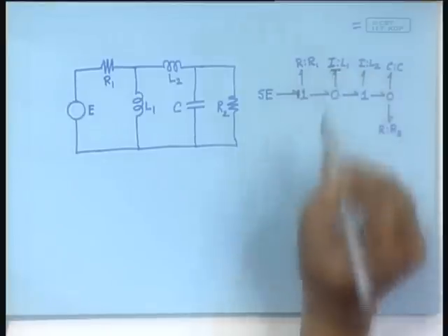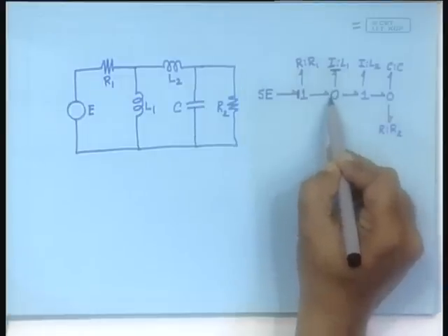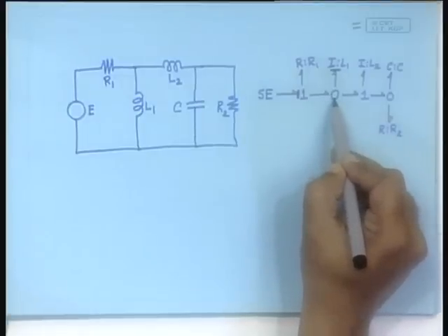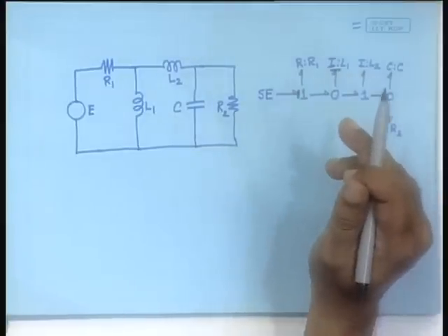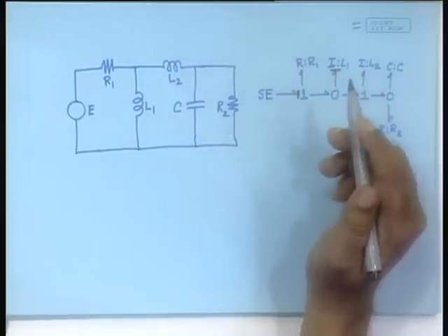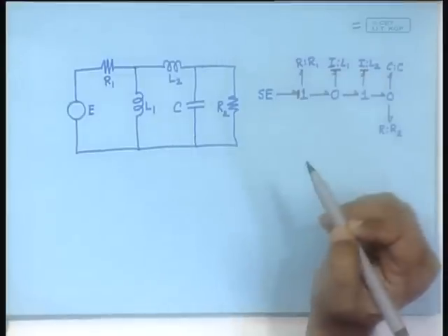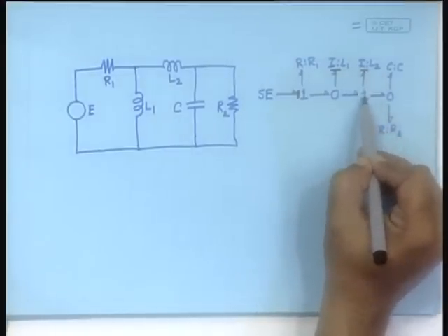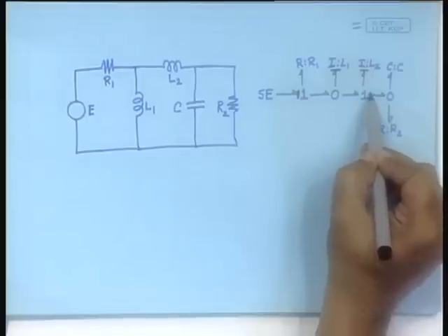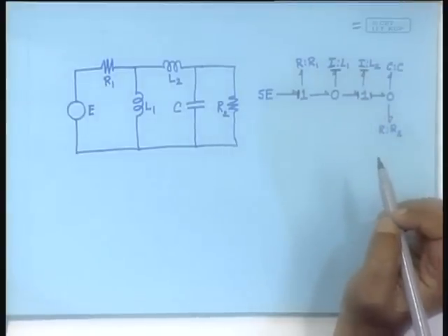So, here we will first put this, which means that the I element is receiving the effort information and giving out the flow information, and it has come to the 0. It is not yet causal, because 0 will be completely causal if a strong bond brings in what information? Effort information. Okay, so let us move to the next one. Here let us put this. The moment you do that, the flow information has come into the one junction, and therefore the flow information must go out of the one junction. So these two are immediately causal. Fine.